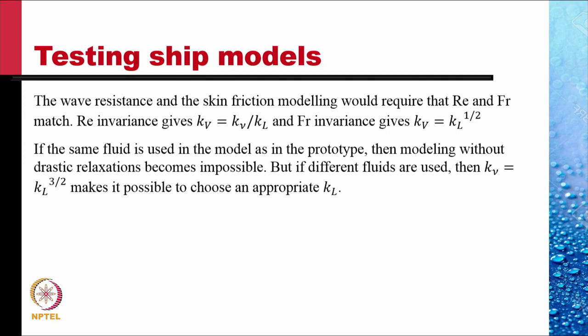Testing of ship models. We are interested in finding out the drag on the ship. The drag on the ship as it moves in open ocean consists of two parts. One, the viscous friction, termed as skin friction, on the surface of the ship in contact with water.